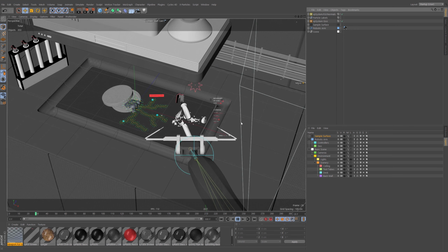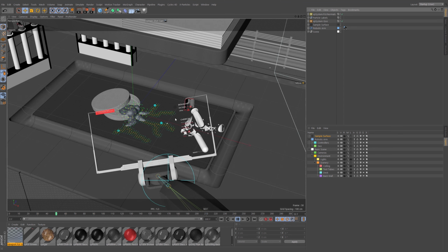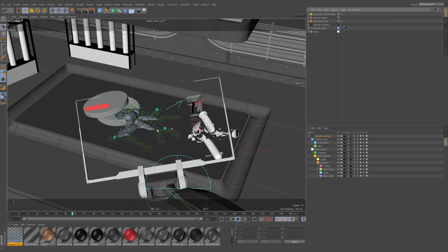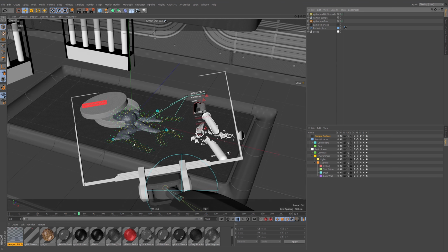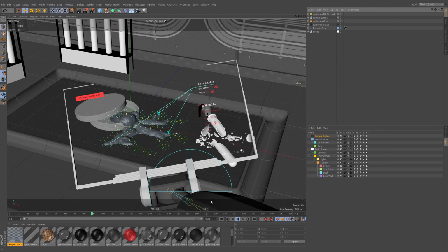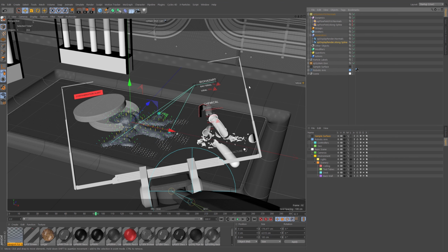Remember, this is only a template, this thing in the scene at the moment. It'll be wiped out in post. So that's looking pretty cool. Now, I'm not so sure about the lines on the ground because it is a predictive thing. But what we could do to make that look a bit more interesting is actually have it animate. So we can actually have a MoSpline reference the original spline. Let's just do that quickly.